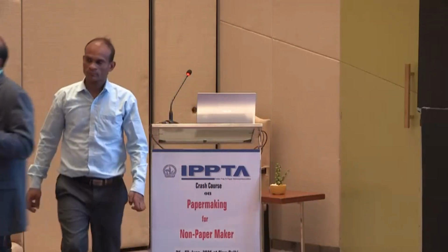Actually it's not a doctor blade, it's water removal ceramic blades. There is a difference between doctor blades and water removal ceramics. We can call them foils or ceramics, because doctor blades are used to remove water only from rolls.